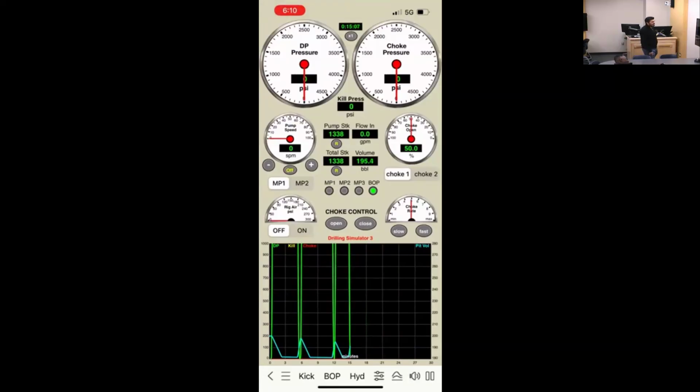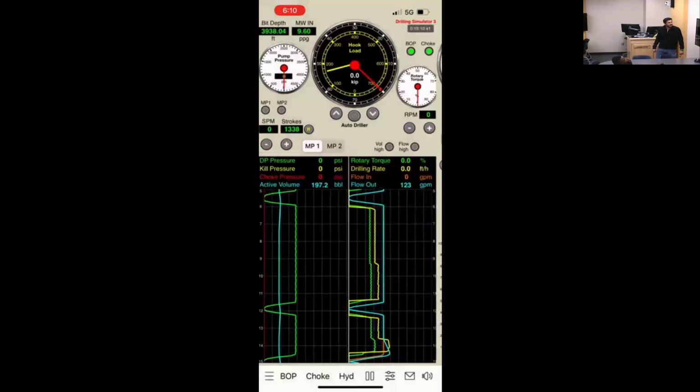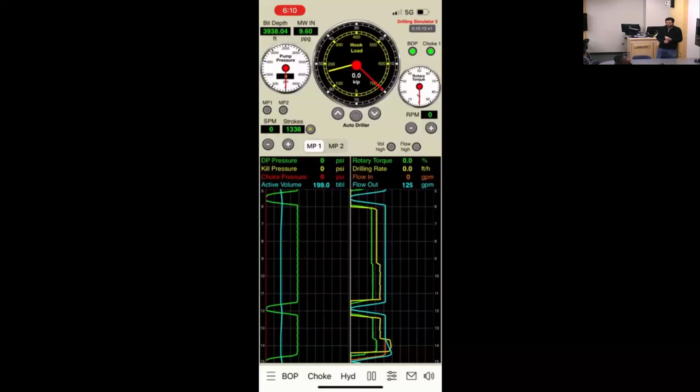So what I need to do is shut in the well. I will basically close the blowout preventers. And how am I going to do it? I will divert. Did I do it or not yet? We haven't done it yet. Now I'm going to go in, set BOP, enable, close the upper pipe ram, and then I will divert. Mud goes in through here and comes out. It doesn't show the casing, but I'm going to make it come out from here. Yeah, there you go.